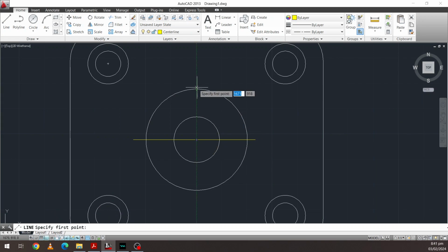At this point, you can even use more than one point as a reference while you're using object snap tracking. So I can place my mouse on the center like that. Then I can place it on the quadrant. Then I can place it on the other quadrant. So you'll see that 3 points here are highlighted. Can be even more.